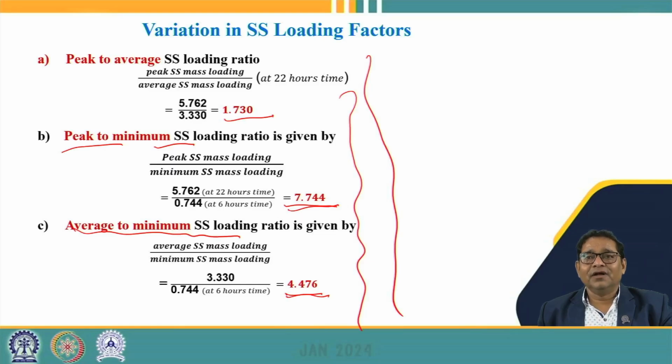So this helps in dampening the fluctuations that occur in a wastewater treatment plant because of variation in the characteristics and variation in the flow rate. This is all about the design of the equalization tank, and how it dampens the variation in the characteristics and flow rates.